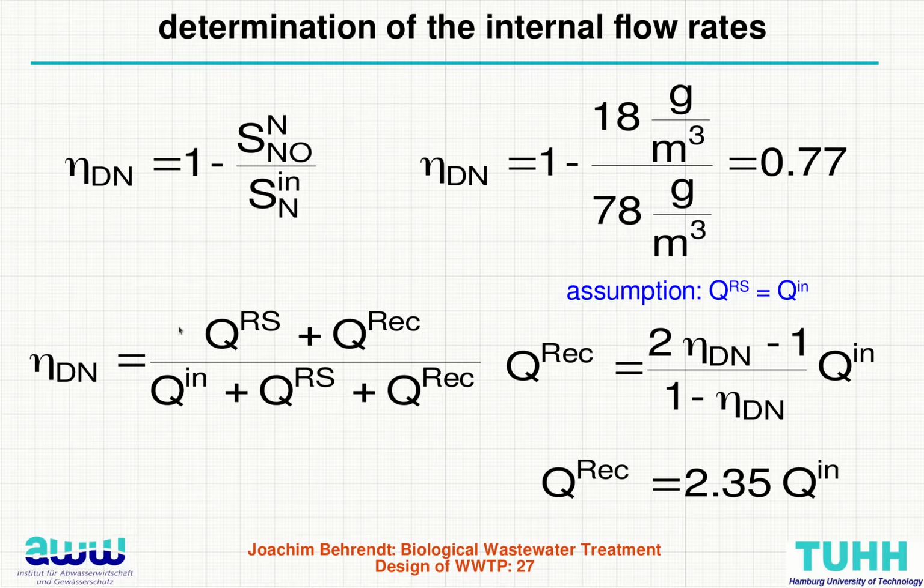Yeah, then we are assuming that we have a very good denitrification. All nitrate that enters our denitrification reactor, as it is mixed with fresh wastewater, will disappear, will be reduced to N2. And finally, the best thing is this: if we return everything, then we have no effluent. But finally, you can end up with this formula: only what you are recycling and bringing back with the return sludge, with respect to the total flow, you can denitrify.